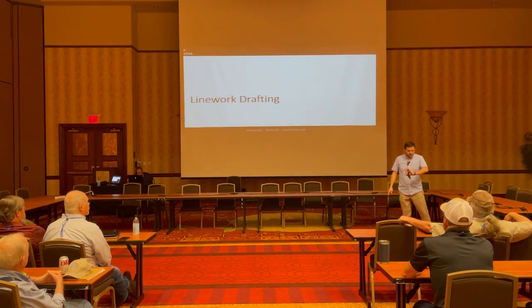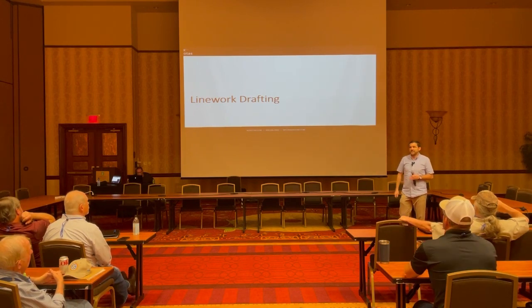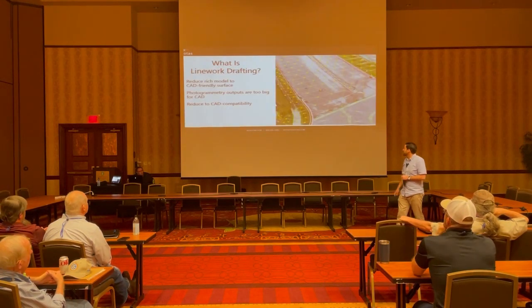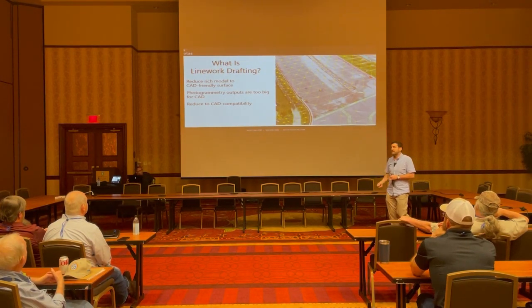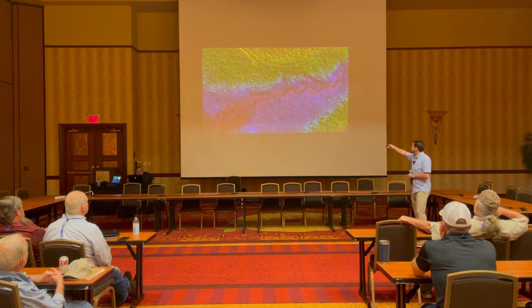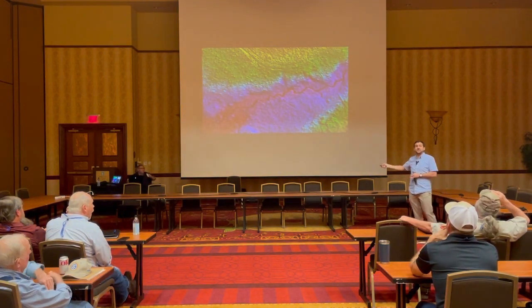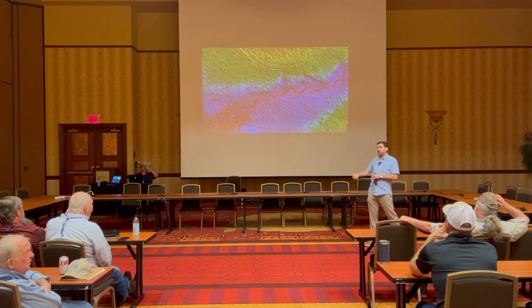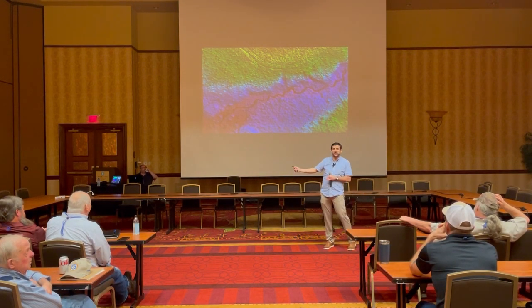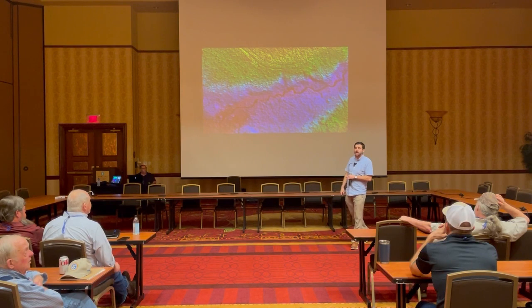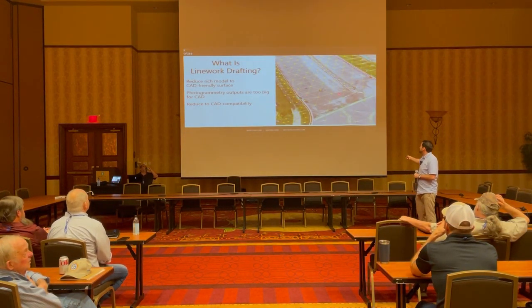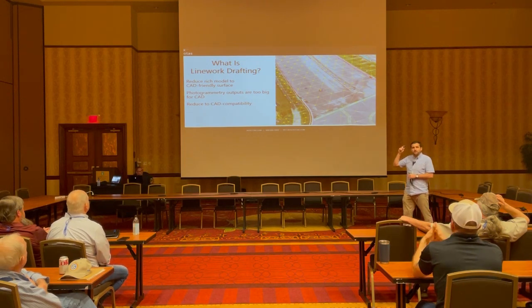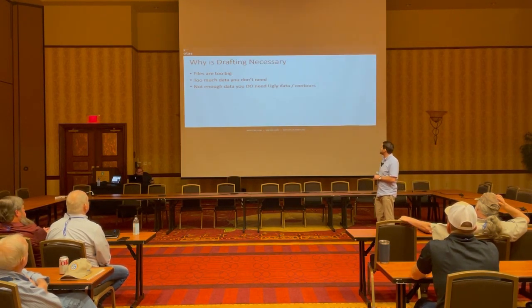All right, so we've got about 15 minutes to go, so now let's talk about one of the last steps, which is line work drafting. So what is line work drafting? As I mentioned, that's when you reduce all of this rich data, even that last photo there, which is still a ton of detail and still going to be a pretty big file. We've taken it from maybe hundreds of gigabytes down to at least hundreds of megabytes, but it's still kind of a pain in the butt to use. So line work drafting is extracting all of these features, curb lines, planimetrics, all of that good stuff.